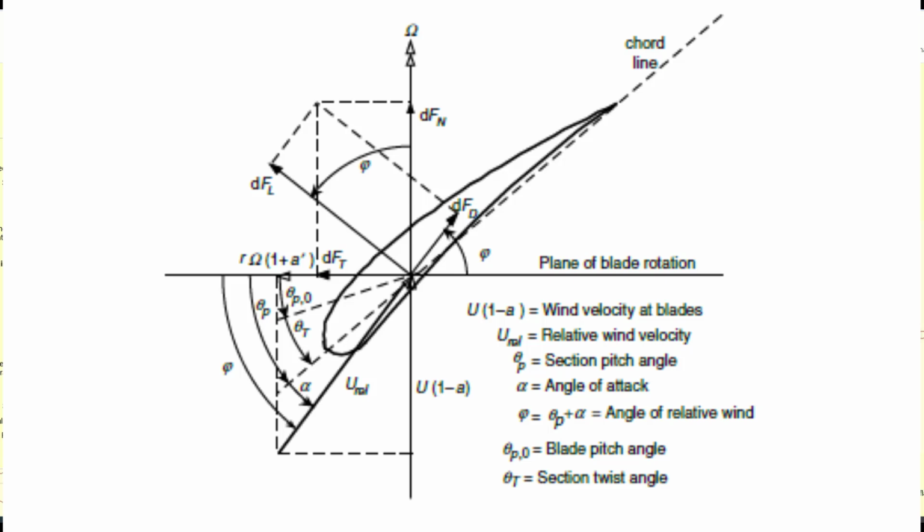So if the ratio is low, it means that there's going to be more drag forces effect. So once you have done one of the calculations, one of the methods, you're able to estimate this lift to drag ratio. With that ratio, you are then able to, in a wind tunnel experiment, select different airfoil profiles that can give you that same lift to drag ratio, but on a reduced twist. In other words, instead of a twist of 0 at the tip and 30 to 45 degrees at the root, you can have a twist of 0 at the tip and 13 degrees at the root, which is much better, in which case it's easier to fabricate such a wind turbine blade.